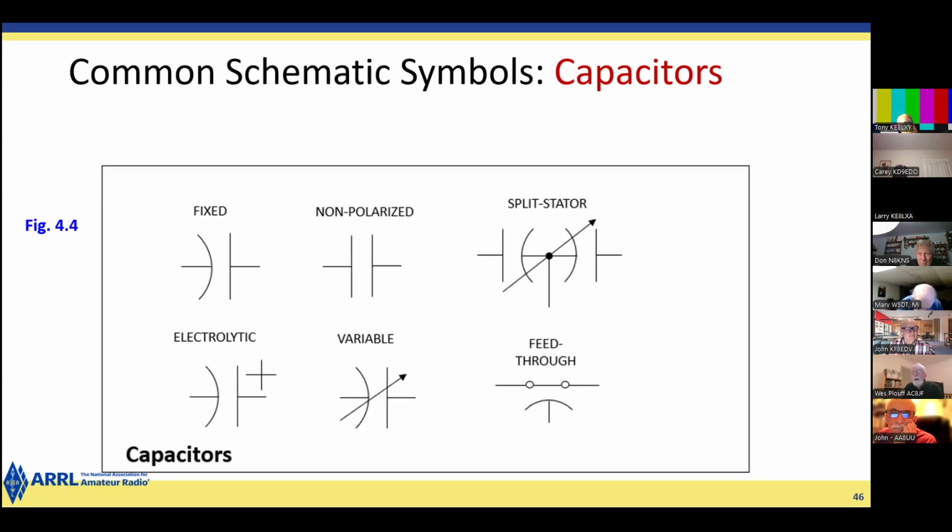Capacitors with large values are electrolytic capacitors, and those are in the tens or hundreds of microfarads. You see those in power supplies, and they are polarized because the plates will be two sheets of metal that are sort of wrapped into a roll, like a Swiss roll, I think, is the pastry.